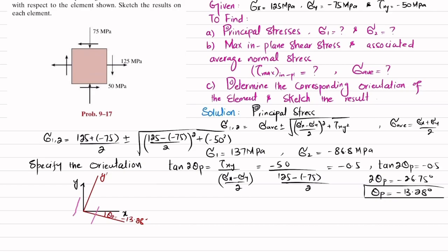like this, so you must know on this face which one stress is acting, either this one or this one. So for that we will use stress transformation equation, and we will put the theta in that. So we know that stress transformation equation is sigma x dash is equal to sigma x plus sigma y divided by 2 plus sigma x minus sigma y divided by 2 into cos of 2 theta.